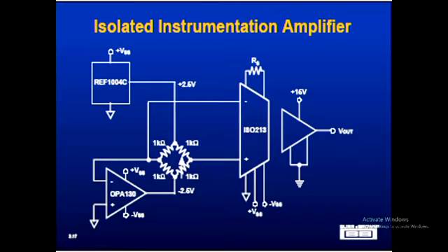Right, good. So the op-amp output is just doing what it needs to make these two inputs track each other once again. Okay. It's tricky, isn't it? Okay, so if this is minus 2.5 volts because this is plus 2.5 volts, we've got 5 volts across that bridge. We've got 5 volts across this potential divider on that right-hand side of the bridge. Yes?